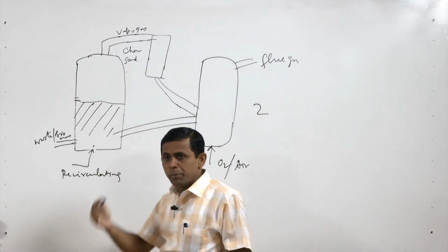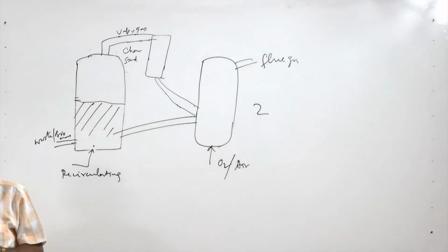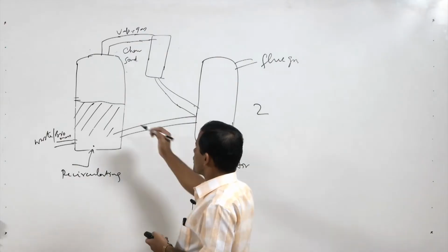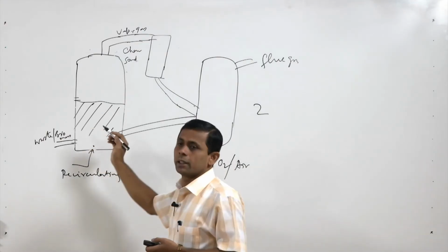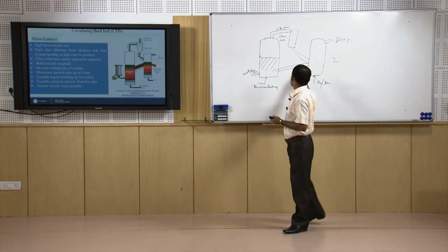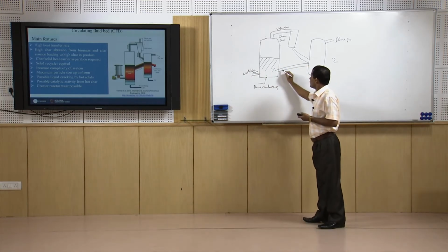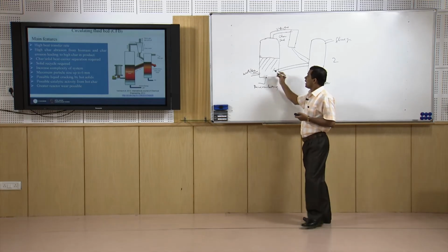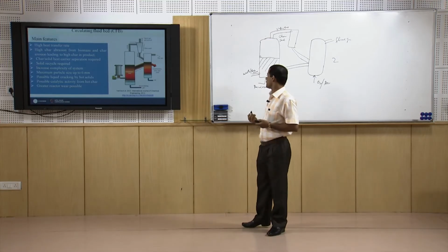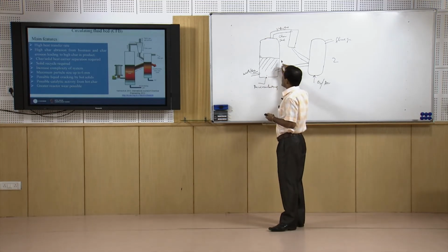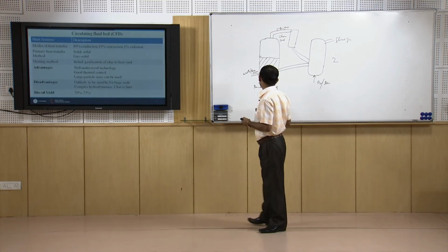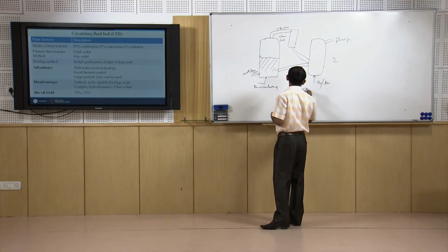So, this is the development of the fluidized bed reactor. Some part of the solid is recycled. Heat transfer takes place here through conduction, convection and radiation, and the char or the sand which is returned can act as a catalyst also, having some catalytic activity. Due to this reason, the bio oil production is also very high, 70 to 75% bio oil.